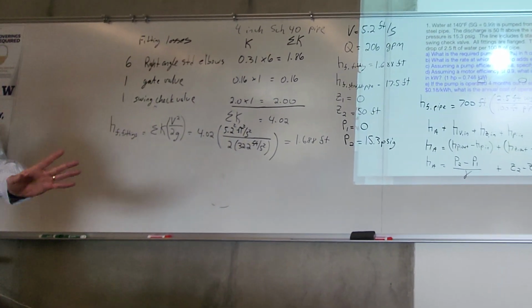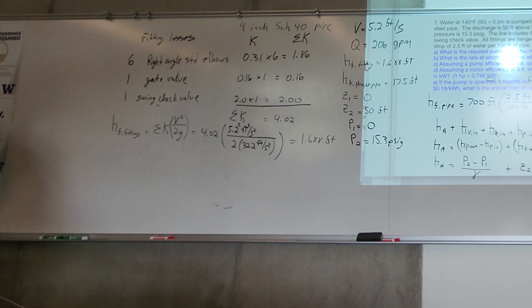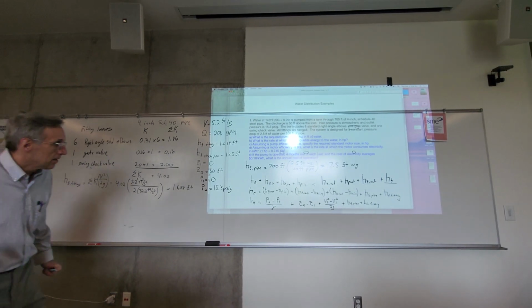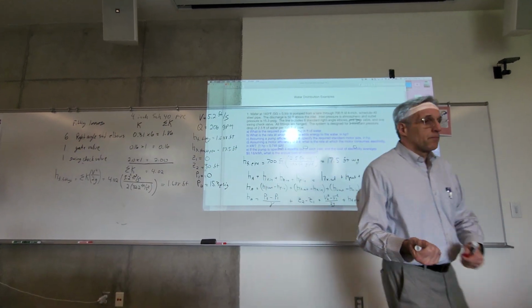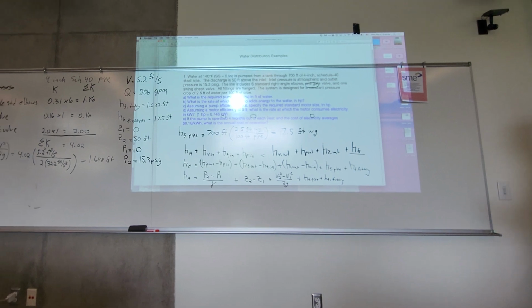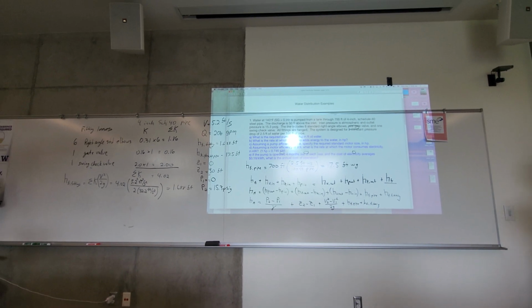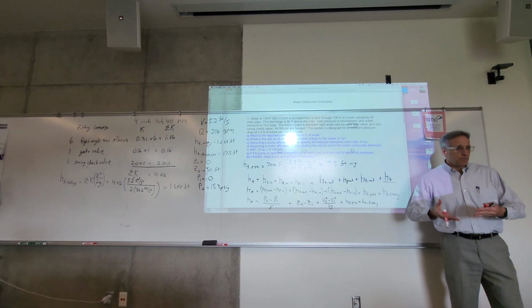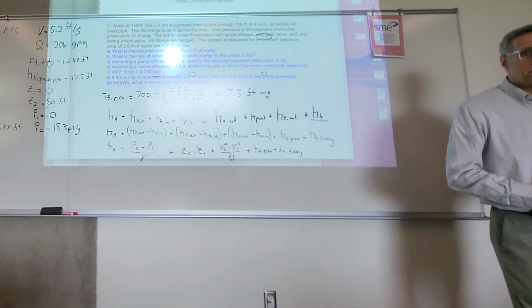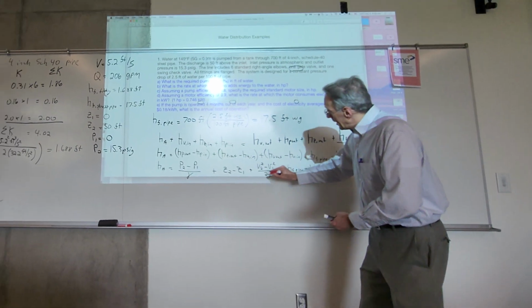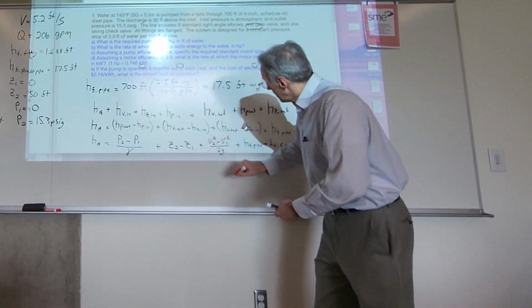What do we do about the velocity term? What would you think? Did we set it to 0 before the pump? Well, pumps do not really change the velocity unless the pipe size changes. Sometimes our outlet pipe size will be different from the inlet pipe size, and that will change the velocity. But usually this is insignificant.